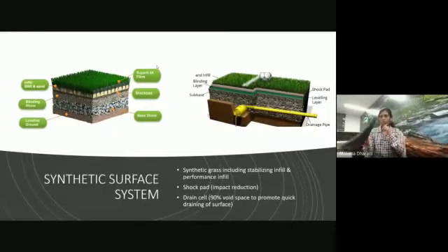So this is what a synthetic grass carpet will look like. See in the back, it's got latex in it, and then there's yarn. The size of the yarn or the height of the yarn will keep varying depending on the type of the game. There'll be 60 mil, 40 mil, or whatever. So that's the height of the yarn. So inside this synthetic grass, there will be two types of infill in it. This is just a carpet itself. If you see that drawing here, there are two types of infill in it.